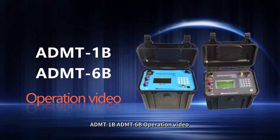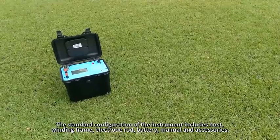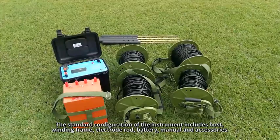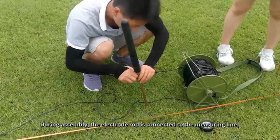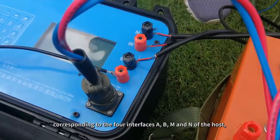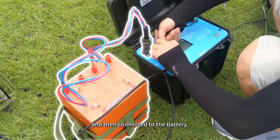ADMT1B, ADMT6B, Operation Video. The standard configuration of the instrument includes host, winding frame, electrode rod, battery, manual and accessories. During assembly, the electrode rod is connected to the measuring line, corresponding to the four interfaces A, B, M and N of the host, and then connected to the battery.